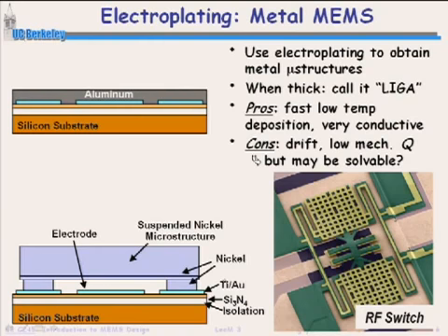Then you're etching into that aluminum to create anchors. And now what you're doing is you're electroplating. Okay, so you're actually growing a film in this. And you can grow it so that it's flush with the surface there. That removes a lot of topography. Topography is our enemy, and so we'll talk about that later on too.